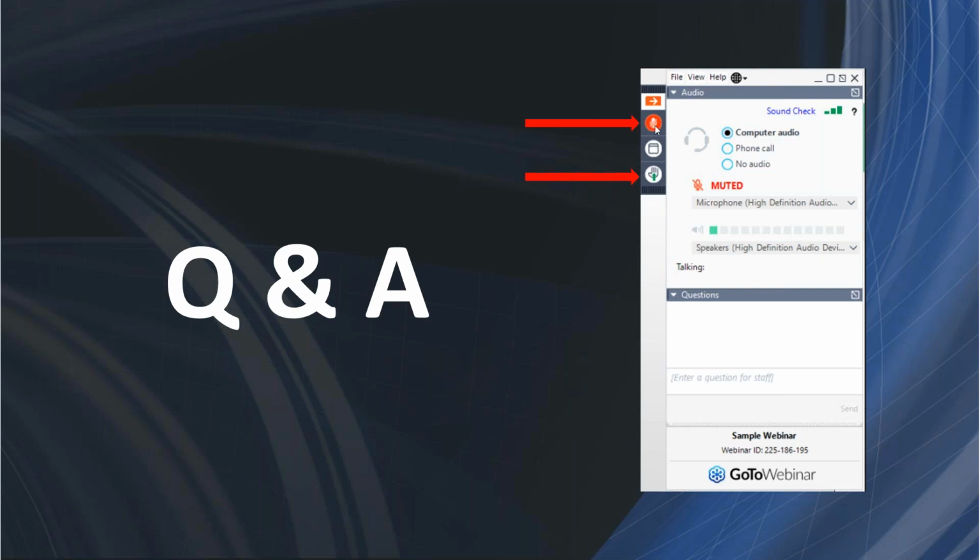Yeah, when it comes to determining the optimum filling sequence, there is a trial and error method, and that's one of the reasons we opt here at CAE to use midplane models, because we can do a lot of simulation in a short period of time. If you're building full 3D models and using valve gate sequencing, it sometimes takes a long time to run these models. So the choice of simulation model type is important to be able to run a lot of simulation in a short period of time. But there's nothing in Moldflow that you can set up to automate this process to give you an optimum filling sequence.